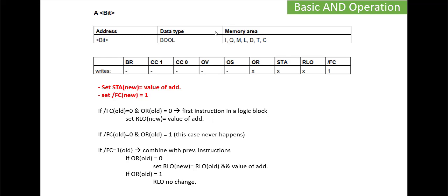This address can lie in any memory area that is addressable for the PLC. As examples of addressable memory areas, we have the inputs, the outputs, and the memory, the local data stack, and so on.